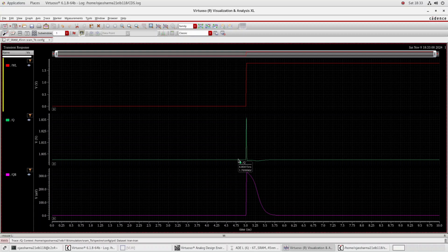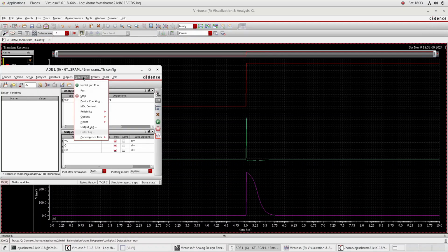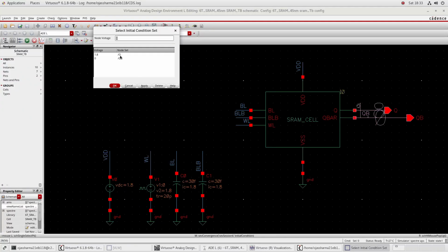As for my initial conditions, I haven't changed them, so yep, it has to be my read 1 operation. I'll go and simulate for read 0 operation as well. Read operation just means that what has been stored at the Sram, it must exactly copy it out the same as well. You can actually see the disturbance state as well.